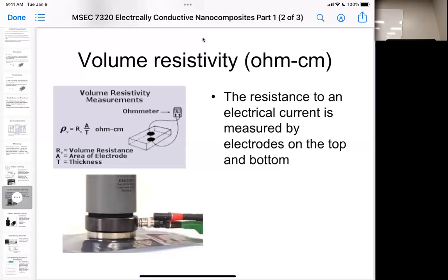So how do we obtain it, actually? Well, for this one right here, this is the top electrode, the weight is the bottom electrode. And it can measure down to like 10 to the minus 18 Siemens. So if you can't measure it, you just get a thinner sample. In fact, a great thing to do would be to make 3 thicknesses of sample and see if it gives you the same 3 numbers when you account for the thickness. Did that answer your question?